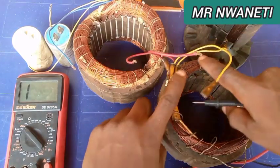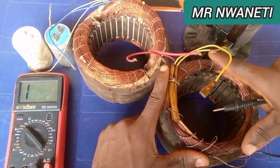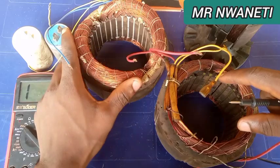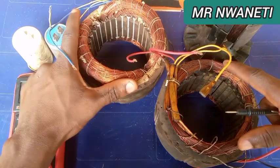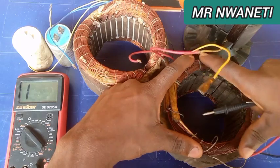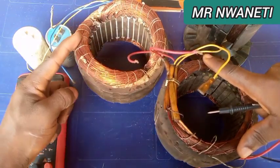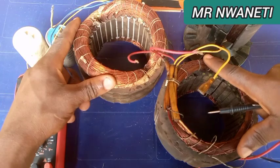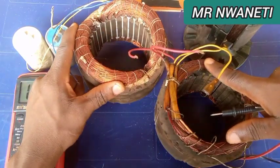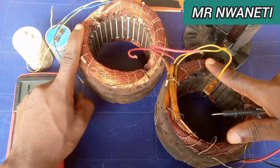So remember, this stator here is unmodified. It is a factory winding. This coil here, I have already modified it. They use 0.7 mm enamel copper, then I reduced it so that I can put more turns. They use 0.7 here, and I use 0.6 mm here to enable me to increase the turns.